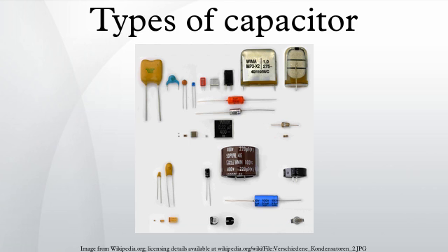Ripple current generates heat within the capacitor body due to the ESR of the capacitor. The ESR, composed of the dielectric losses caused by the changing field strength in the dielectric and the losses resulting from the slightly resistive supply lines or the electrolyte, depends on frequency and temperature. For ceramic and film capacitors, ESR generally decreases with increasing temperatures but rises with higher frequencies due to increasing dielectric losses. For electrolytic capacitors, up to roughly 1 MHz, ESR decreases with increasing frequencies and temperatures.